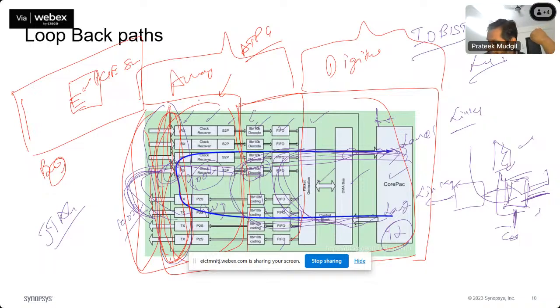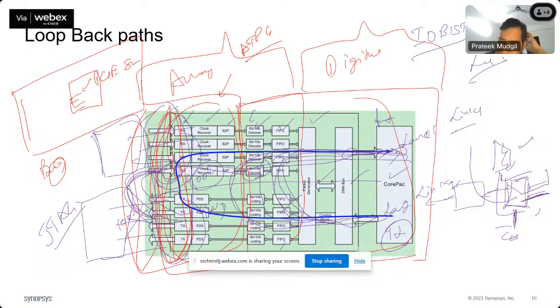Or we can do one more thing. Let us say our transmitter is working fine, the receiver is not good, so the test fails. What we can do is put a dummy tester receiver and send the data, and if it is properly received by the tester, we can say that, okay, this path is clean. Then we put a tester and send the data not from here, and it goes here, right, and we say that, okay, the receiver path is not good.